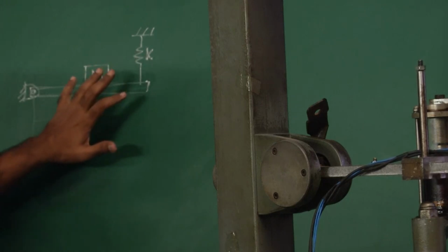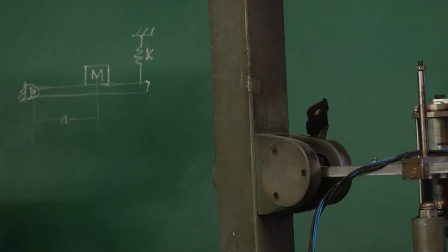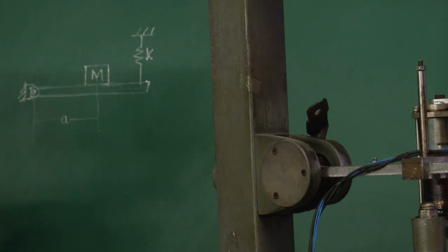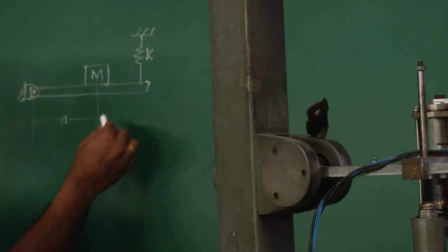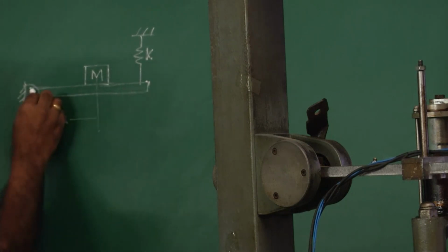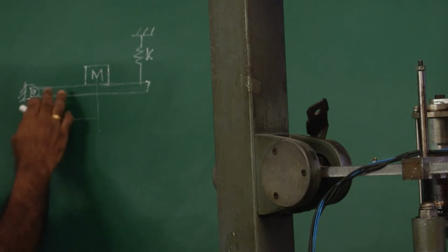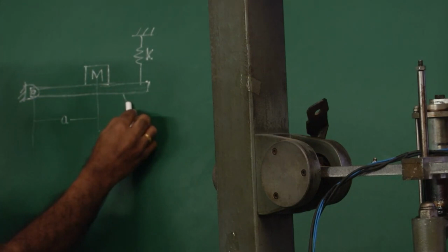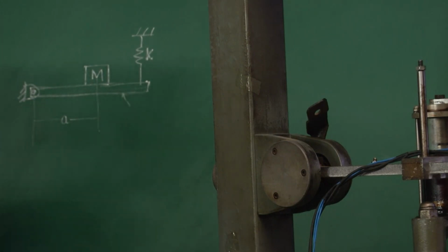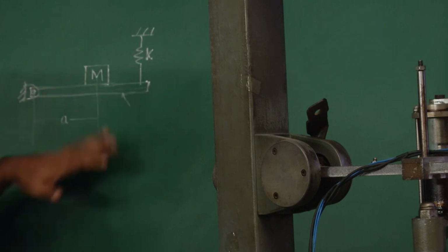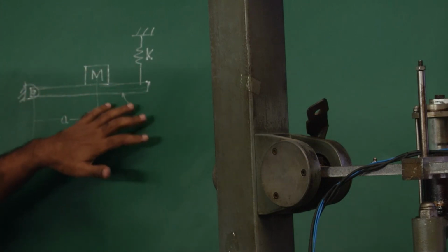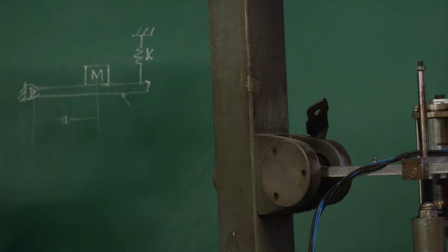And the mass of the motor here is going to store much of the kinetic energy of the system. Now, this beam being hinged here, for the small oscillations that are taking place, the beam is expected not to undergo any bending. Okay. So, the beam behaves like a rigid beam, and so therefore, the mass of the beam may also store some part of the kinetic energy.